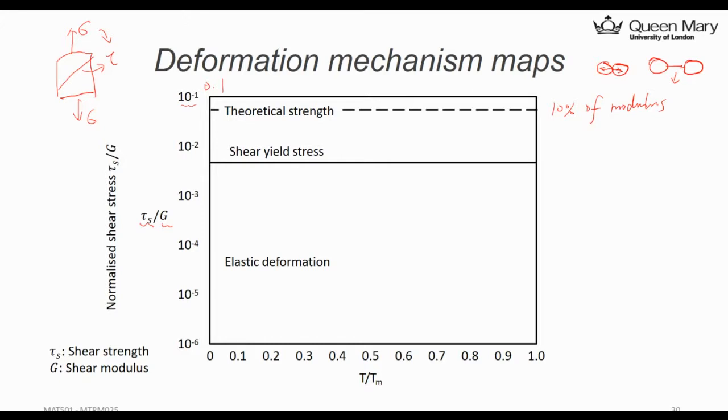And if you look at the shear yield strength, once the shear stress reaches the shear yield strength, tau_ys, which can again be related to your uniaxial stress, it is about 1 over square root 3 of the uniaxial tensile yield strength. You can go back to our previous lecture and find this relationship. So at this point, you will reach the plastic deformation.